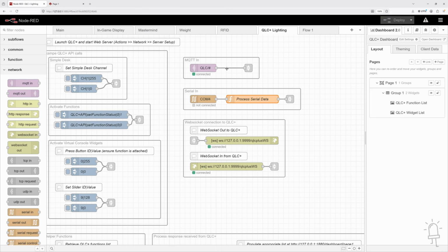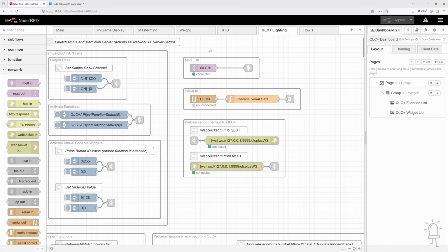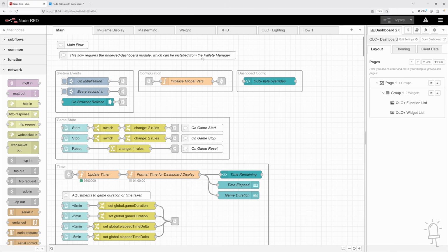This approach is much cleaner than scattering hard-coded DMX channel commands in your ESP32 or Arduino code. And it also makes the system easier to develop and maintain. You can change the aesthetic look of a scene, adjust the lighting or add effects in QLC Plus without changing the node logic, or you can change the logic of the game flow without risking or having to rebuild your lighting scene. And while this allows everything to be automated, you can also include manual triggers or overrides that an operator uses from a dashboard. So this can become your complete theatrical room control software.